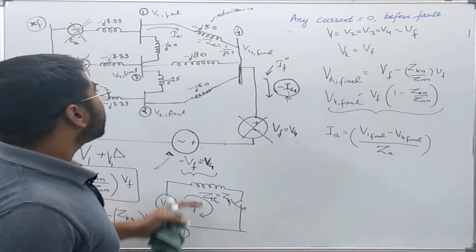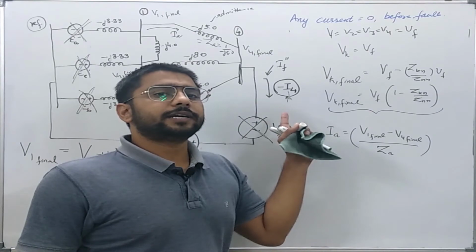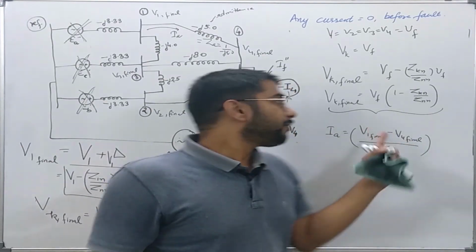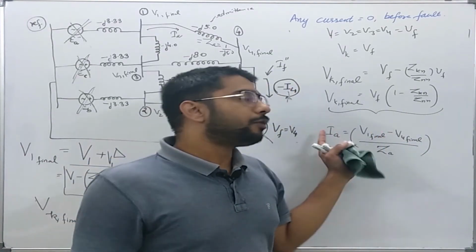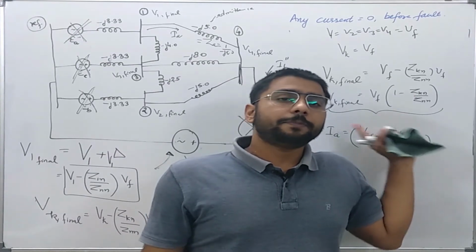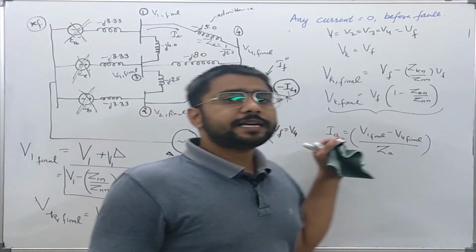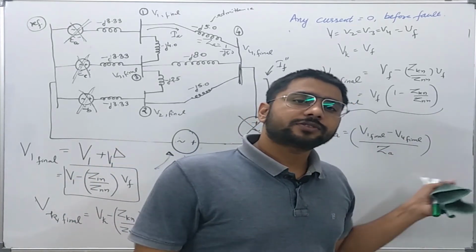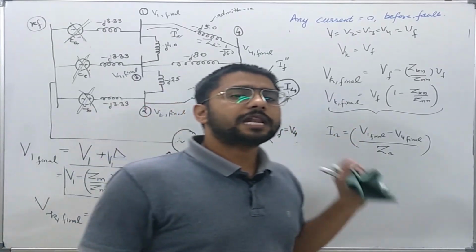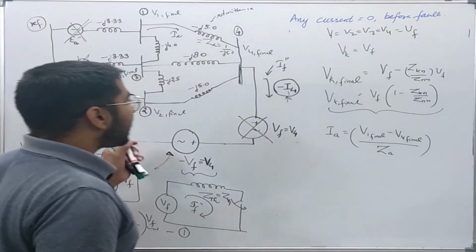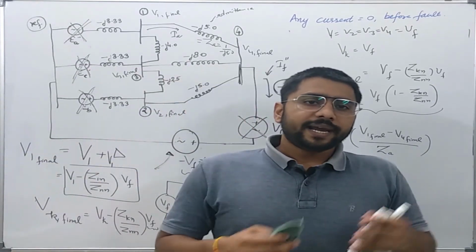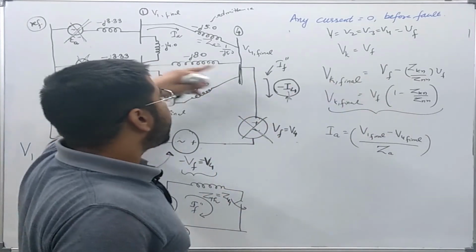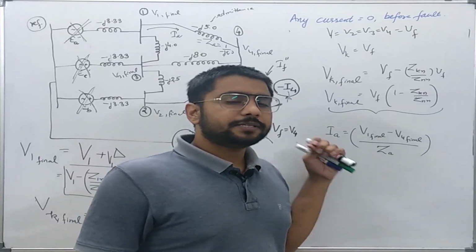So in this way, I can find all the currents in the given power system once I know the bus voltages. Now you see that the bus voltages are easily found if I use the bus impedance form of the equations instead of using the bus admittance form of the equation. So in this way, we can clearly see the importance of the bus impedance matrix during fault calculations. Now in the next slide, I will try to make a very crude equivalent structure in terms of the various elements of the bus impedance matrix that we will see in the next slide.